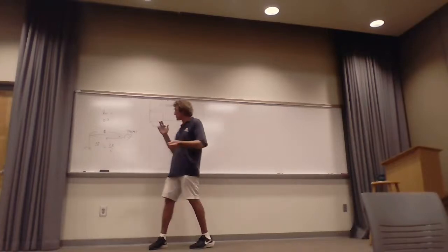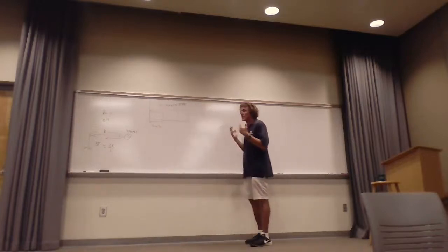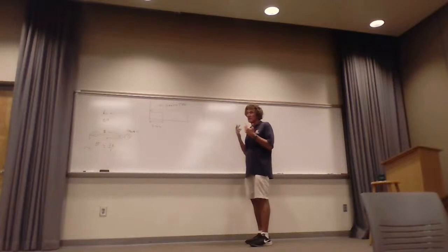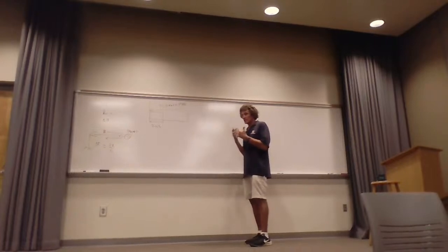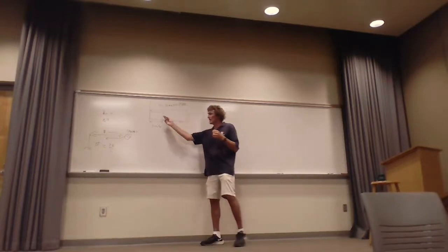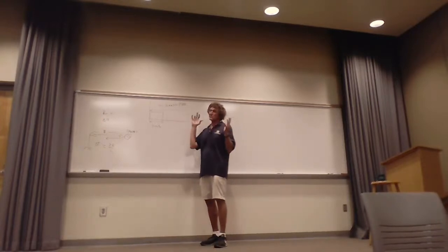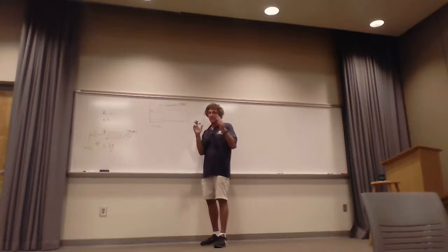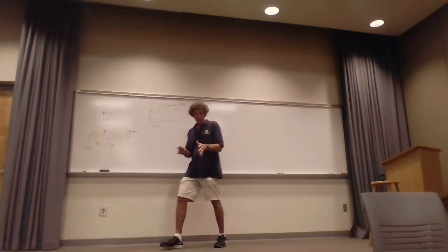Now, what if there's a target further out? Well, if a target reflects further out and its signal is above a threshold, then there is an ambiguous target. But usually what they do is set the ambiguous range, or they set this time, such that for the largest target possible, there's a lot more to this, the signal reflected from it will not be enough to cause a triggering event where you'll say, oh, there's a target. It's going to be too small.